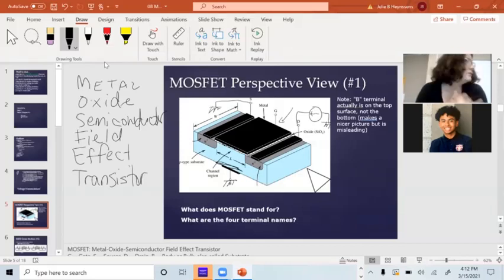If you look at this, the first thing you should notice is there are also these PN junction diodes. I've got an N+ region and a P-type substrate. The junction between them is a diode. Now the drain, the N side, is at a higher voltage than the P side, so no current's going to conduct. I have a back bias diode there. And over here between the source and the body, if they're both connected to ground, I also have a 0 bias PN junction. No current's going to flow through that either. So it doesn't look very useful from that perspective.